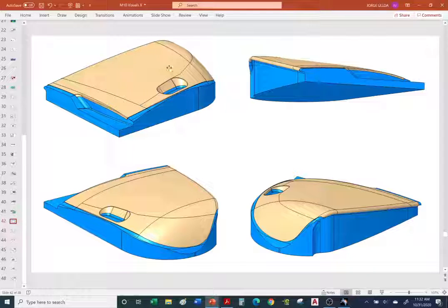Now, because it's prototype, experimental, we're going to use some cheap tools or cheap material. This is blue block. It's like a very hard plastic. So what the tech is going to do is take sheets of fiberglass or carbon fiber and just lay it up on this tool. We can just let it dry on its own with the resin, or you can stick it in an autoclave, or you can heat it up. It'll speed up the process and also give it a stronger bond.